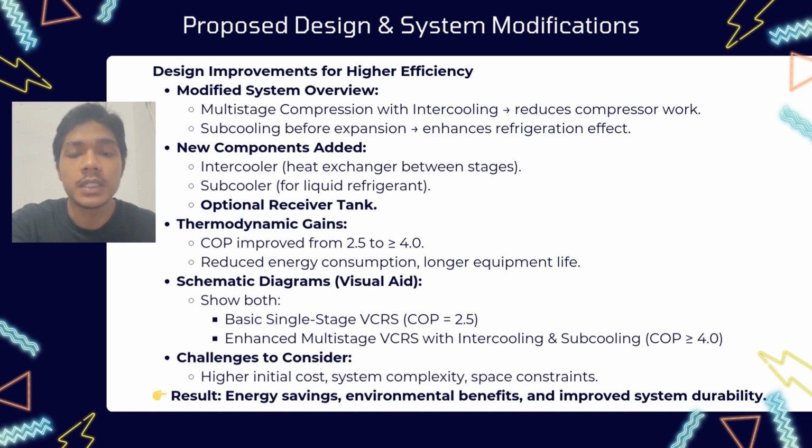With this modification, we can increase the COP from 2.5 to 4.0. This results in lower energy consumption and longer equipment lifespan. However, this improvement does come with some challenges such as higher initial investment, increased system complexity and the need for more precise process control.